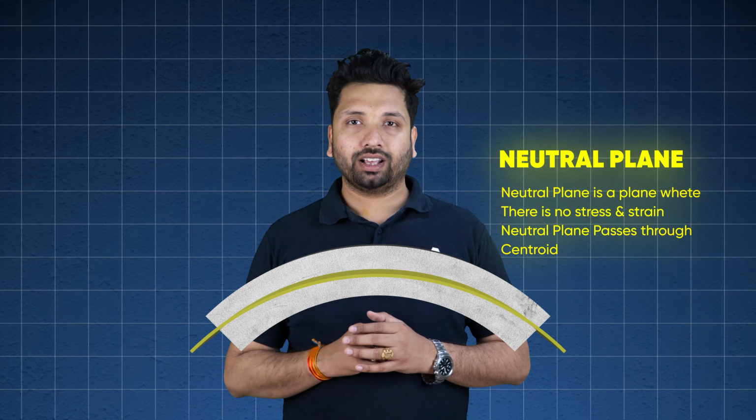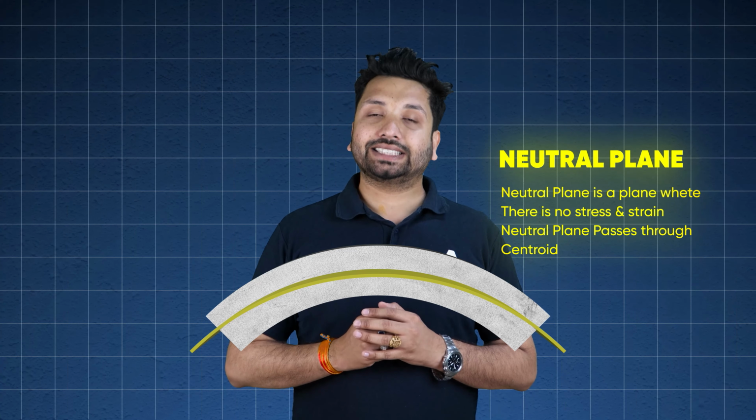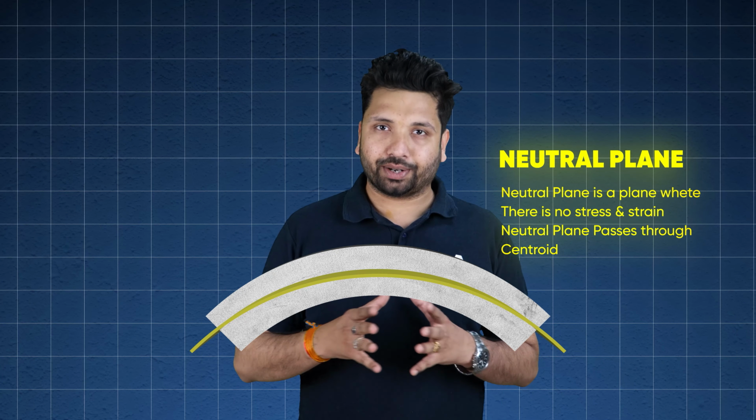Now as I've said, there are tensile stress and strain and compressive stress and strain on the top and the bottom fiber. But there is a plane where there is no stress and strain. That plane is called the neutral plane. One very important point related to the neutral plane is that it passes through the centroid of the cross section.